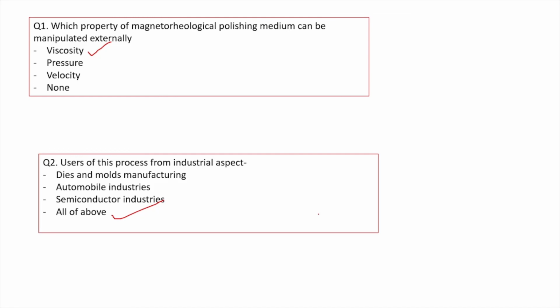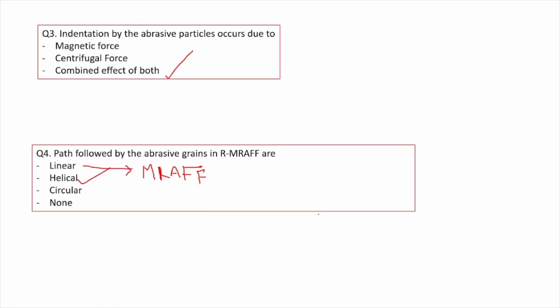The second question is about the applications of the MRAFF process in industry. The applications are in dies and molds manufacturing, automobile industries, semiconductor industries, and biomedical industries. The third question: indentation by abrasive particles occurs due to the combined effect of centrifugal force, that is radial force, axial force and magnetic force together.